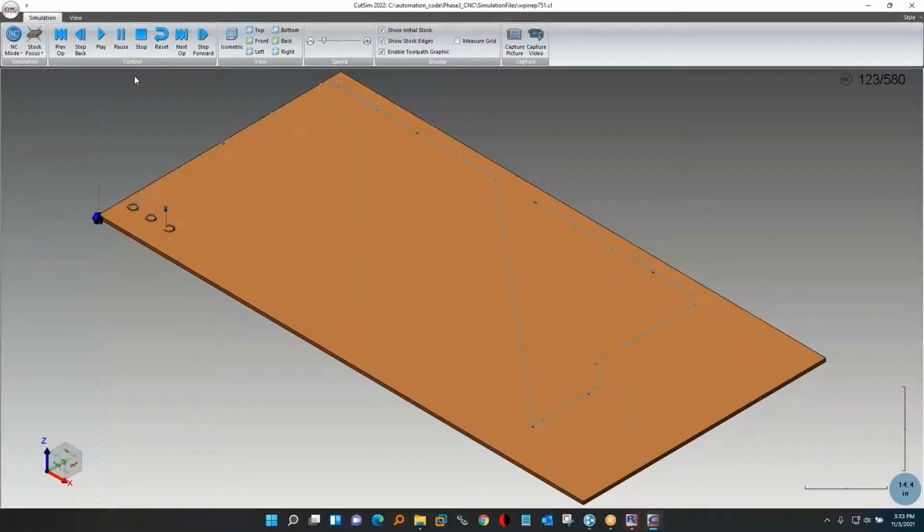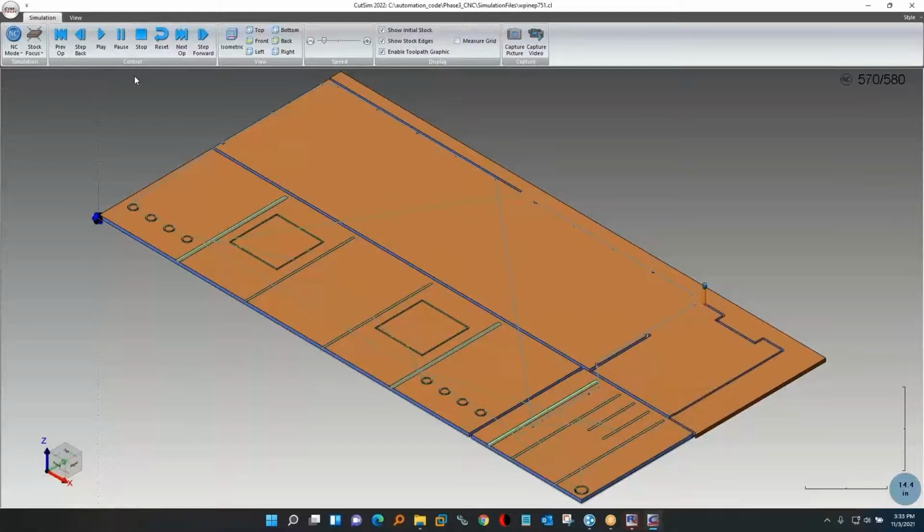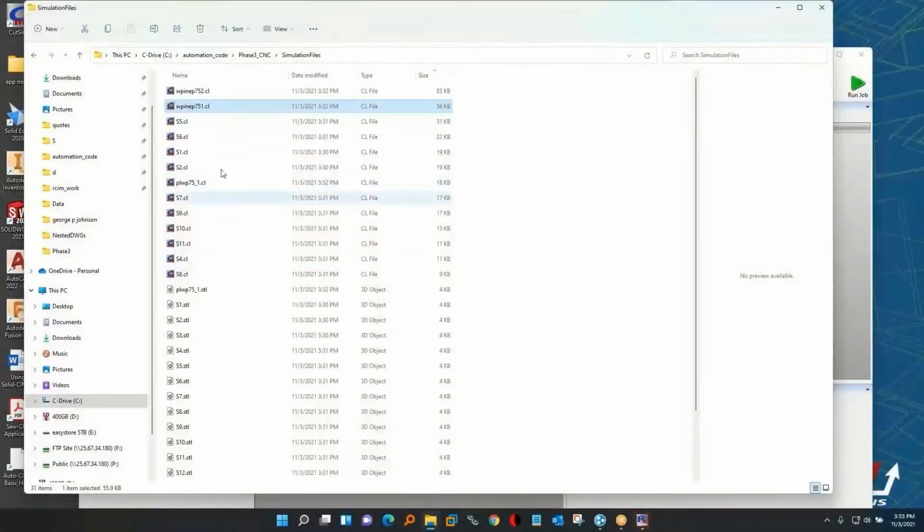We're going to show reporting and so forth, the material usage report, and the labels that we talked about earlier. So this is our cut sim program that simulates the toolpath, and you can pan and zoom this around while it's simulating. This is a way to see the order things are happening. Remember I told you we have these machining knowledges. It's like what tool, feed rate, spindle speed, cut direction, type of machining operation. Well, it also has a rank number, what order to do things in. So I did my drilling first, rank number 1, then insides is rank 2. You can make a rank 1.5 that happens in between 1 and 2, so you're never stuck with any numbers in between there.